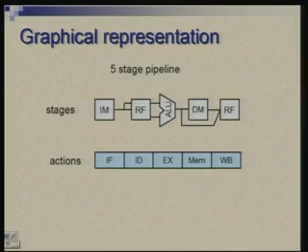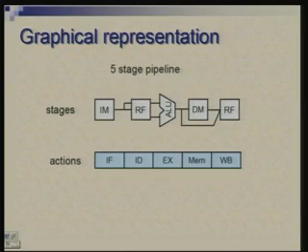Now, let us try to analyze things a little bit. Okay, for that we will not carry that big diagram and I abstract it further. So, you can either show very symbolically the 5 stages which we have: instruction memory, register file, ALU, data memory, and again register file. So, RF I am placing twice because there are 2 different functions being performed here.